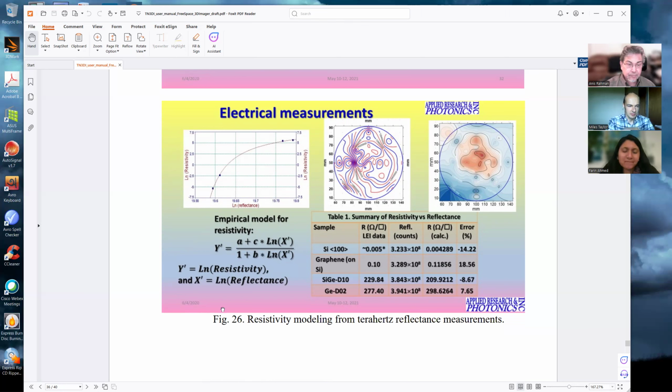The advantage is that once the model is ready, from that point on, it's a matter of just putting the sample in the machine and getting the number instantaneously. It doesn't take any time. And then we can do that 99-point measurement and map the resistivity of the entire wafer. This has to be within certain limits before they can go on manufacturing all the circuits. And if the local variation is very high, then that wafer will not be suitable for circuit fabrication.